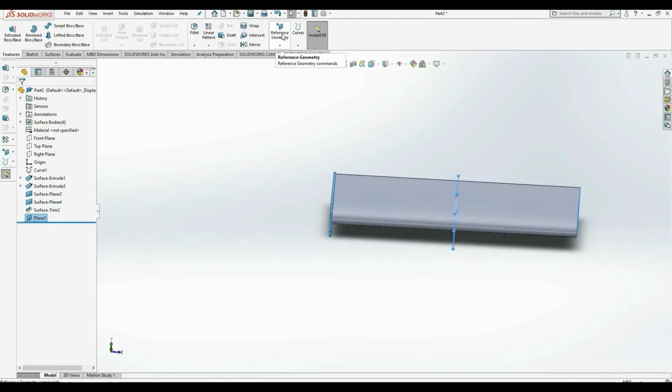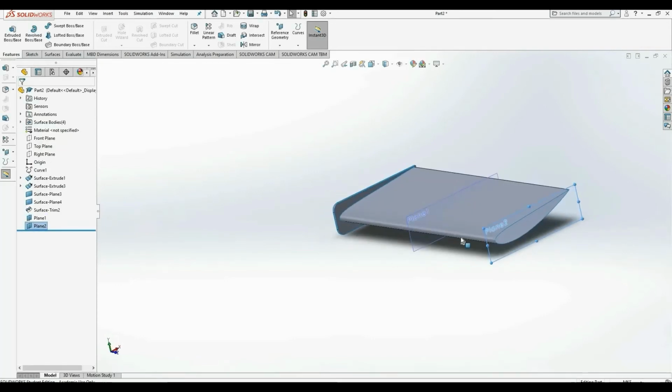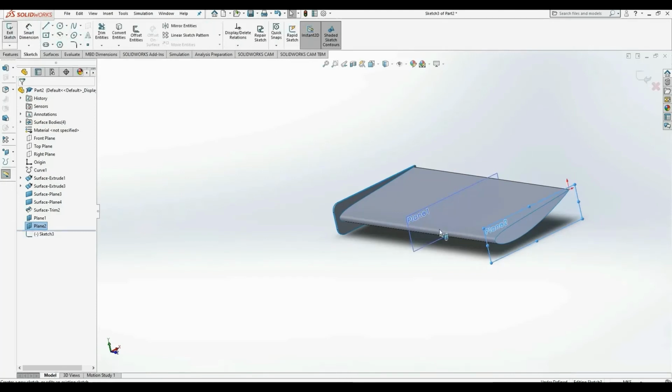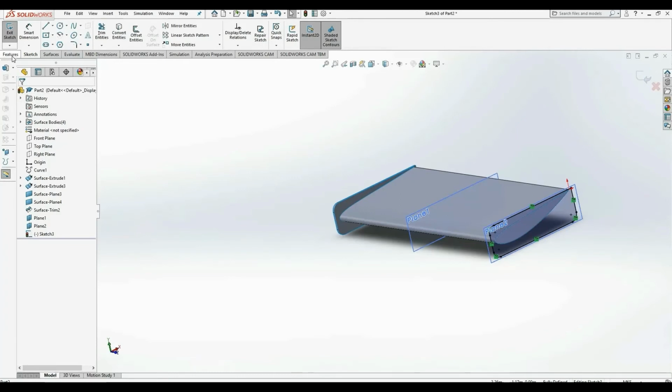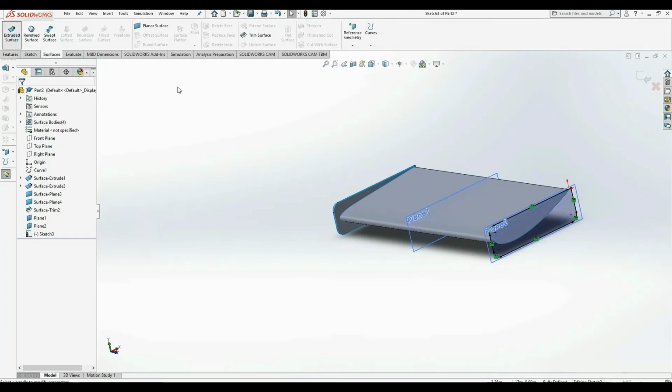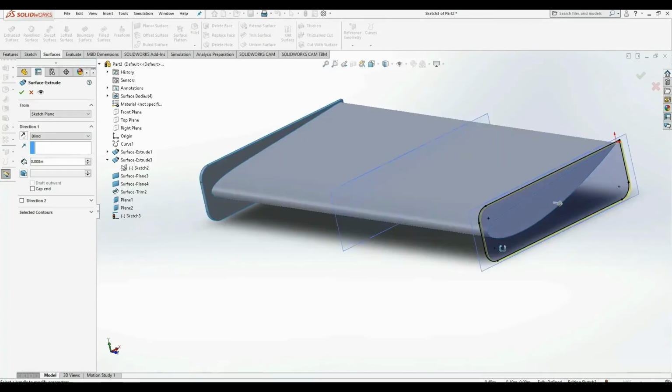I've gone to the midpoint because I might want to change the aerofoil shape through this extrude at a later date if we decide we want to try and create some kind of change in section. Then going on to the other side, we now have replicated the initial plane on the exact other end of the aerofoil. Just be a little bit cautious, make sure you've got the right dimensions. So now if I take over that sketch, so I've got my end plate sketch, we can then follow a very similar practice on the other end. We can create our extruded outer surface.